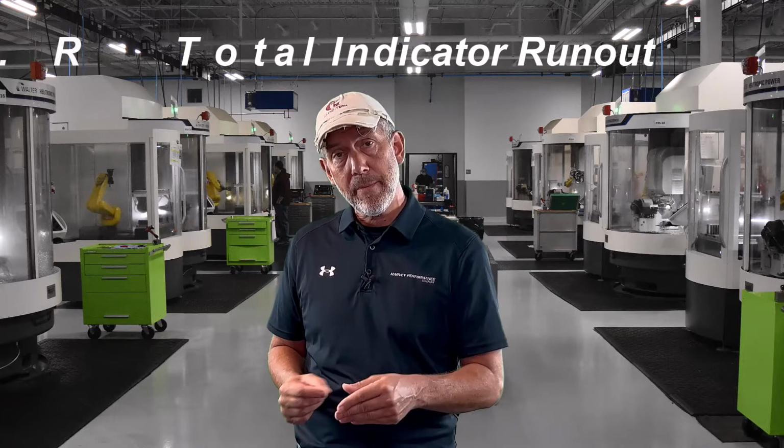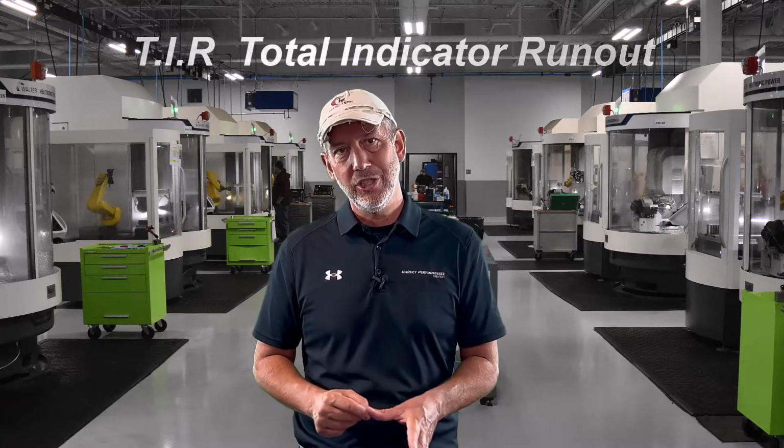So first, let's just talk about making that switch from high-speed steel into carbide. Carbide's stable. Carbide's not going to walk. Carbide's going to create pretty much the hole, if you use the right speeds and feeds, that it was designed to do. The downside of a carbide drill is it doesn't like to move. It's not going to take any kind of movement with the fixturing. It doesn't like any movement in the holder. It likes good TIR because it's going to make the hole that it was intended to do.